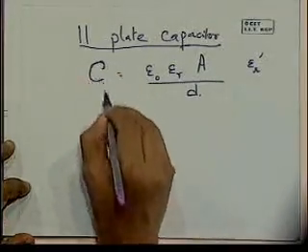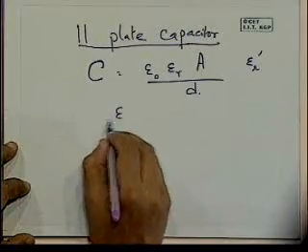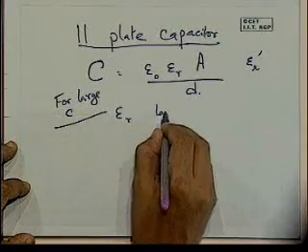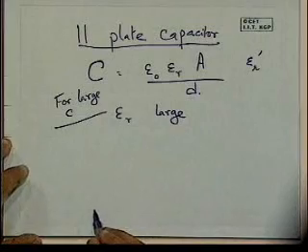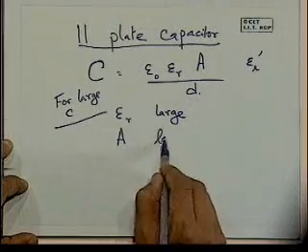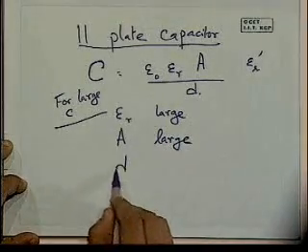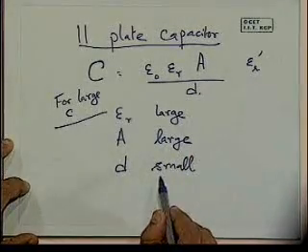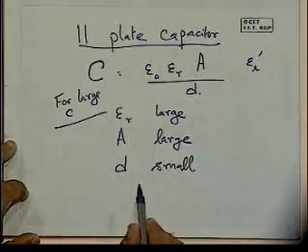And if I want large capacitances, it's obvious that there are three possibilities for large C, namely that I can have epsilon R large, what will be called our high K dielectrics. We'll look at that more in detail. Or we can have that A is large, or alternatively that D is small. And we will see later on what are the advantages and disadvantages of going in different directions, and why particularly for ICs, for chips, area can't be increased indefinitely. There's a problem there. We're trying to make them smaller. And what will happen if we make it thinner and thinner? We'll look at that shortly.